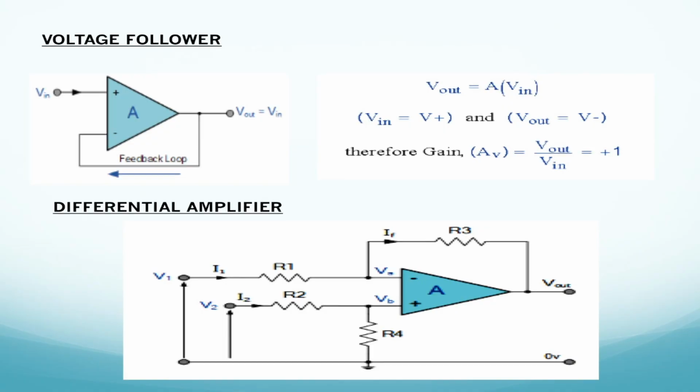Next, what do I go for is that I don't give any resistance, let me go for a negative feedback just without a resistance value. I just go for only feedback and give my input. Most probably this acts as a buffer. Wherever I just need an isolation part, I go with this voltage follower circuit, where whatever input I give, the same output I will be getting, right? Either it is positive or negative inputs.